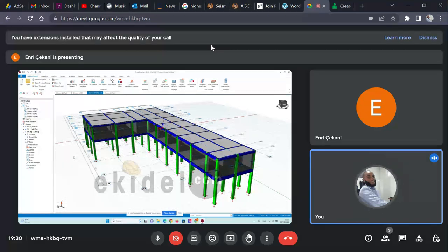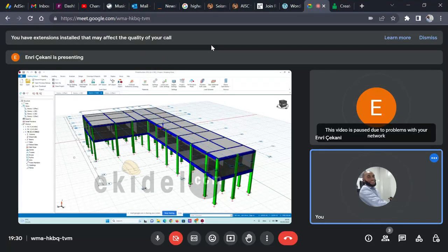So when you're doing a seismic design, you have to consider capacity design by protecting, first of all, columns, which are the main element, and then non-ductile elements like beams, and most times shear walls. Although shear wall is considered a ductile element, most people still consider it, most times, as a non-ductile element.